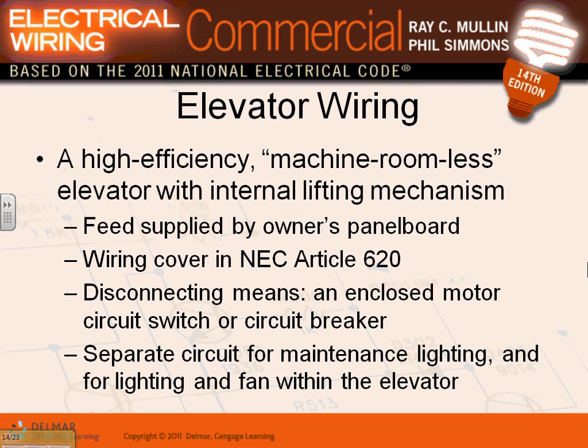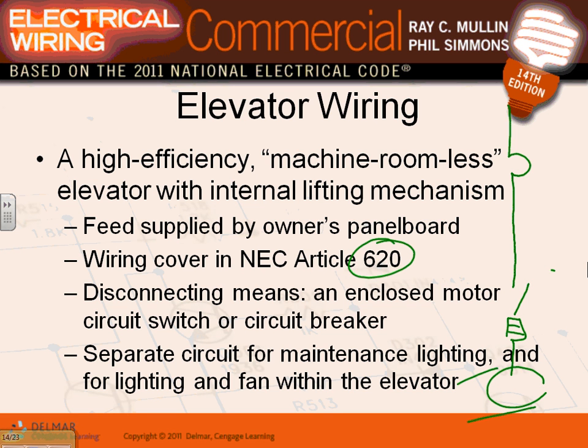So when you size for an elevator, you size exactly, guys, exactly like a motor, right? You take 1.75 for a fuse, 1.25 for the conductors. A few things, guys. We're feeding it from the owner panel. The article that talks about the elevator at this point, and I'm not going to make an elevator class, is Article 620. Here's what you need to know. You need a disconnect means for the elevator. So here's my elevator, overcurrent protection device coming here. Here's my disconnect. I have to have a fuse disconnect. And here's the pump for my elevator.